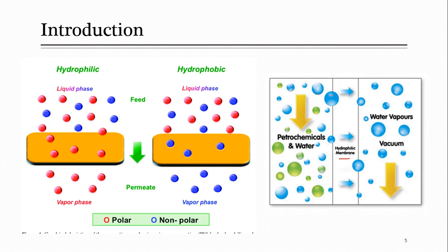Now here, when we are decreasing the pressure, we are creating the vacuum. When you decrease the surrounding or ambient pressure, the boiling point is reduced, and they can easily boil even at low temperature. Due to this, they are converted to vapor. For example, if we consider water at ambient pressure on this side, you would need a temperature of 100 degrees C, but when you reduce the pressure, it can definitely boil easily even at a temperature below 100.